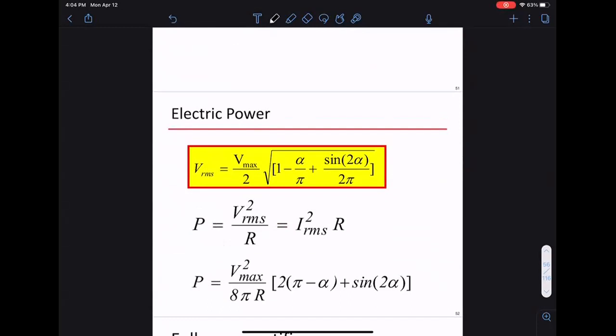Yeah, I had a question. Sure. So is that RMS of the voltage something that could be used for the controlled half-wave rectifier and the regular half-wave rectifier? Yes, for the regular one, you put alpha equals 0. I see. Okay. So half wave. This is alpha equals 0. Plugging alpha equals 0, all the equations work. Thank you.